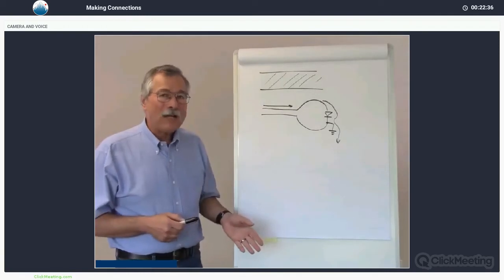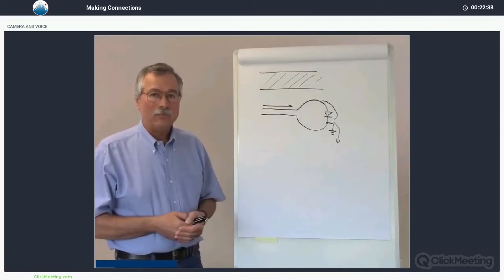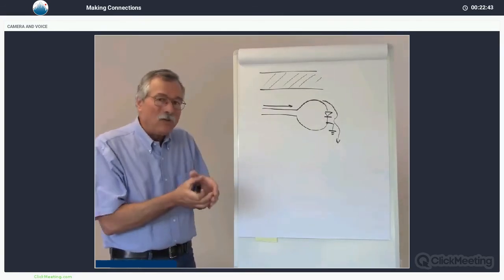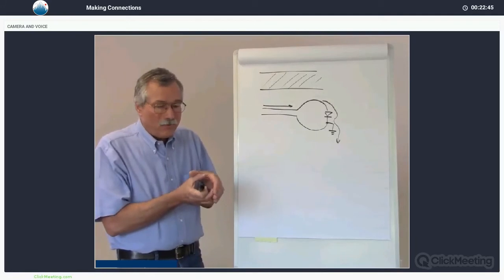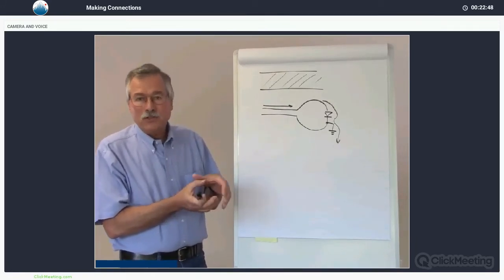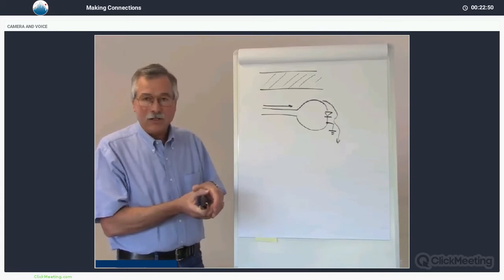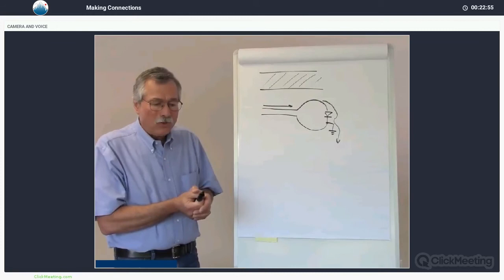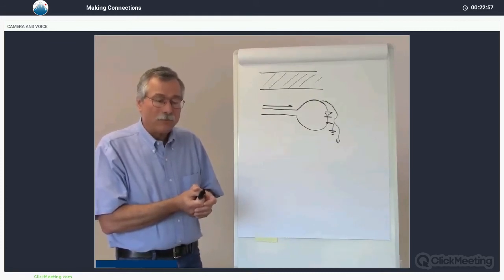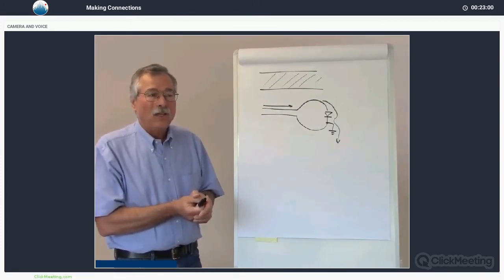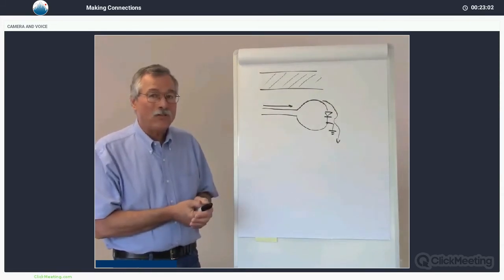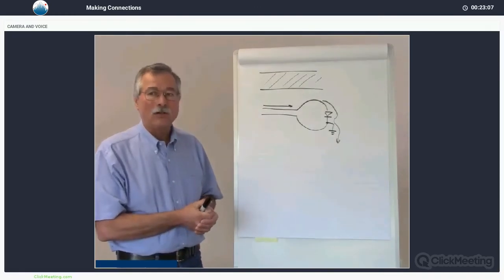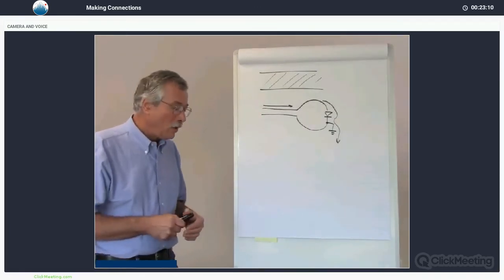And I really put current probes at the bottom of the list as accurate ways of looking at the pulse. One of the reasons, as we mentioned before, is that it's hard to get a current probe around a strip line. So it forces us to use a small round wire, which is an inductor, and messes up our envelope that way. The other issue is most current probes are really not very fast, and probably won't give you an accurate representation of what's going on unless you are hitting this with really deep pockets. Good current probes are very expensive.